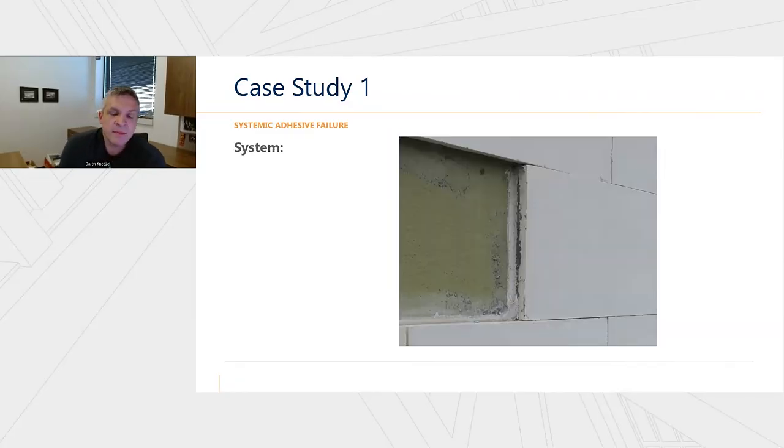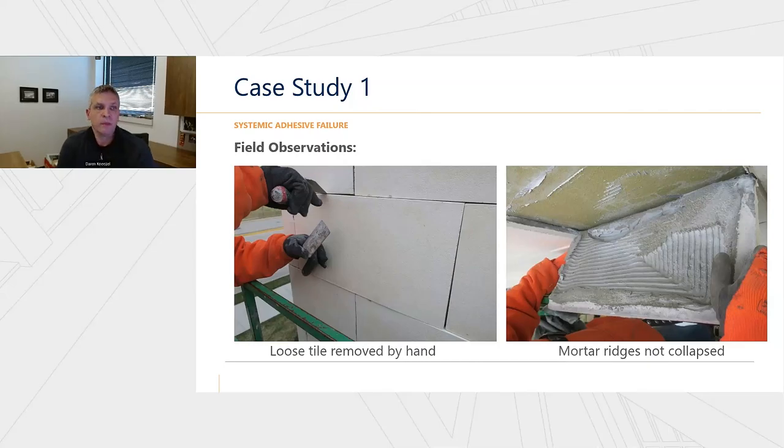The system included 1-inch thick manufactured stone veneer, a polymer modified thin set mortar at the plane indicated by that arrow, where you're actually seeing sealant because it was an inspection opening, but there's mortar at that plane. There was a fluid applied air and moisture barrier over cement board backup. At the perimeter there was no joint material, no sealant or mortar, so it was a dry stack system.